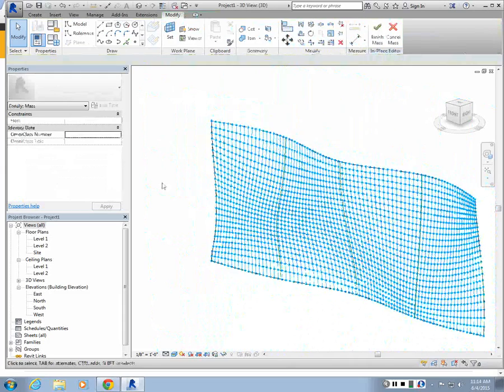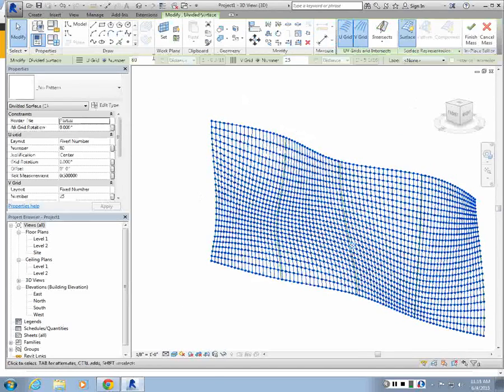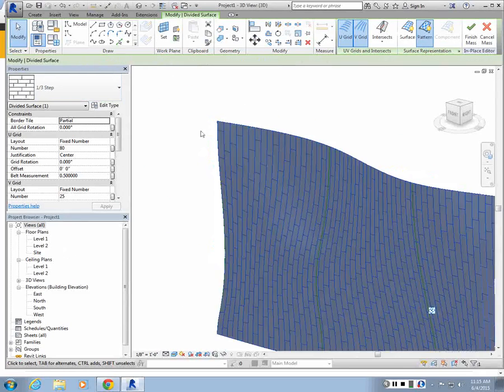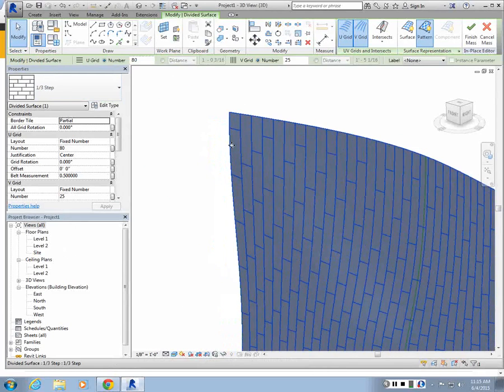So it places these UV coordinates of the control points for division. So the one that I control here, I have vertically 25, horizontally 80 points. And then if I choose any type of pattern here, it will use those points to give me the corresponding pattern configuration. Yeah? You changed the color of the material before you changed the pattern, right?